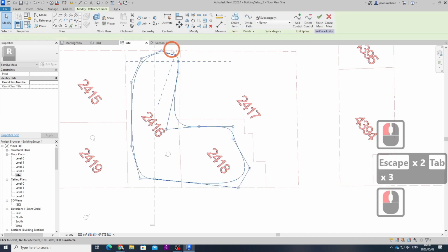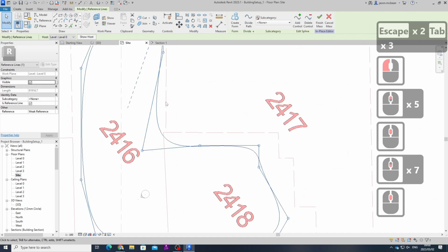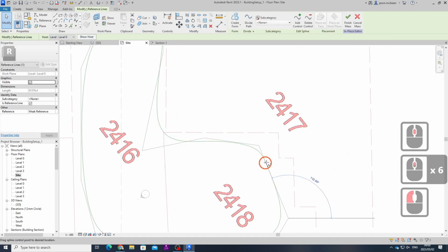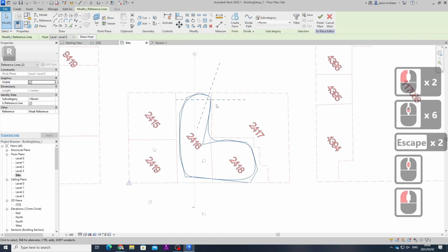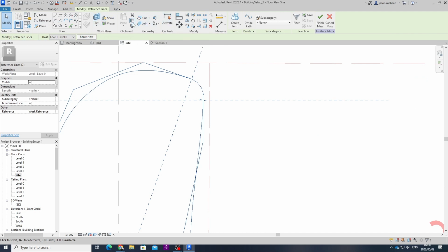And we just tab. Now, because the spline was linked to an arc, you have to tab until you select just the spline to make some adjustments. I'm just making some adjustments. Good. Now, I'm going to grab all of this connected line work. I'm going to go to the copy command. You'll see here, copy to clipboard.